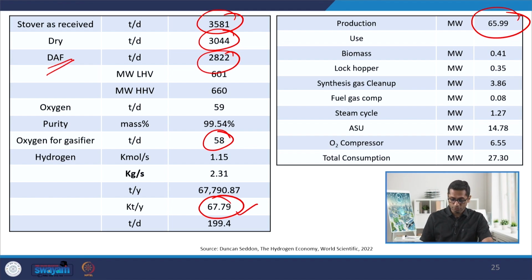This is going to be used for the biomass handling, the lock hoppers, the Rectisol unit, which is going to clean up the syngas, which is going to have significant tars, and these tars are basically liquidy compounds, a consortium of maybe more than 200 compounds, all higher molecular weight compounds, and this is a problem for the downstream operations.